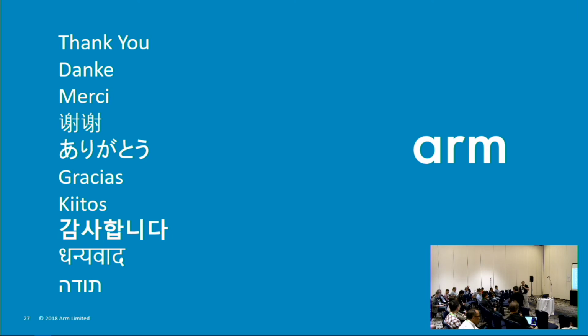There's a pair of counters in the ETM. So we set one to run for 5,000 clock cycles, and the other one then runs for a set of further 5 sets of 5,000 clock cycles. So effectively, when the trace is on, you run 5,000 clock cycles with the trace, then switch off for so many sets of 5,000 clock cycles, and then the state machine comes back round to switching the trace on for 5,000 clock cycles. At 2 levels. Yeah. All right. Thank you.